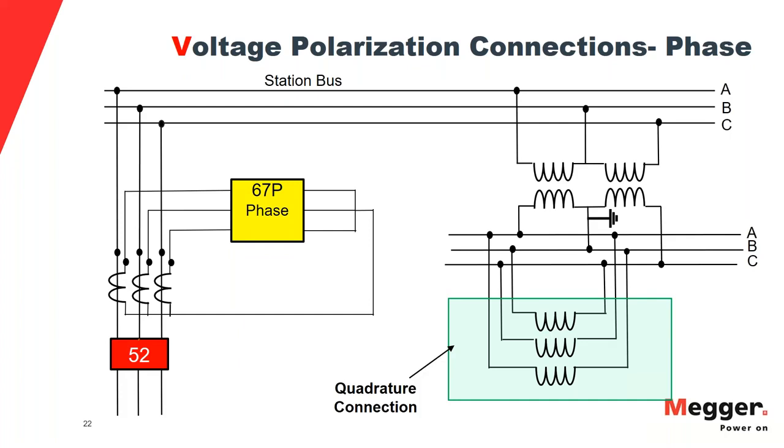All right. Next question, on the different polarization options, which is the one you recommend? Positive, negative, or zero sequence, supposing you have all options available? It's a very open question. I can say it depends, actually. The positive, negative, zero sequence selection depends on the application where you are using it.